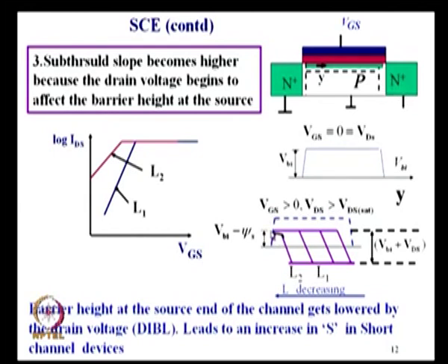So, what was getting reduced by psi s by VGS gate voltage, now will be a combined effect of the gate voltage and also drain voltage, which would mean the reduction in this barrier height, which gives rise to your current, is controlled by gate and also the drain. Okay. So, the gate loses complete control over this reduction, part of it is taken care of by the drain region.